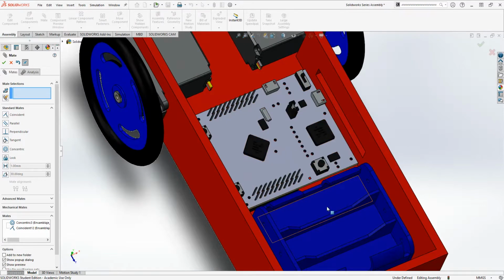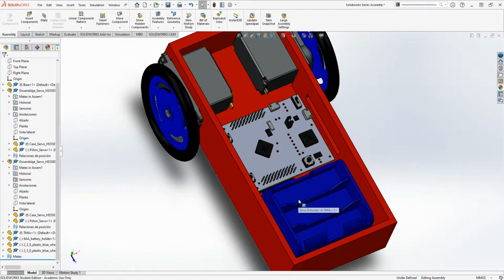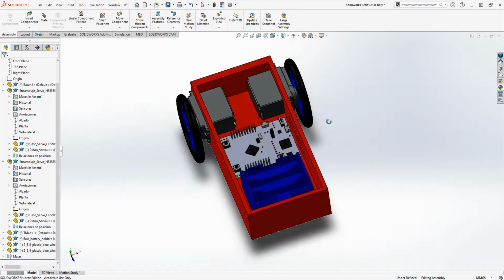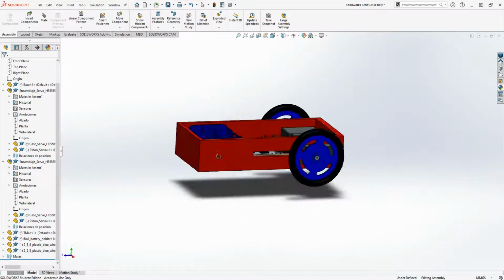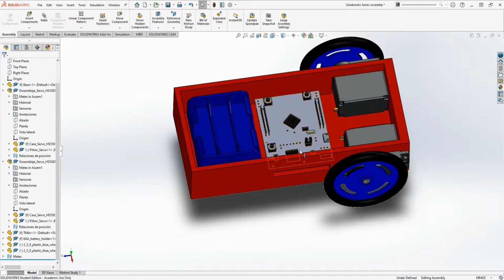So we're just going to stick with some cylinders. Let's make sure this is lined up along the axis. You could take this circle, this cylinder, and mate it to the other cylinder. So what we could do is make sure this is concentric. Great. Now you can see, because there are two cylinders, it's restricted not in rotation, but along the axis you could put it in.